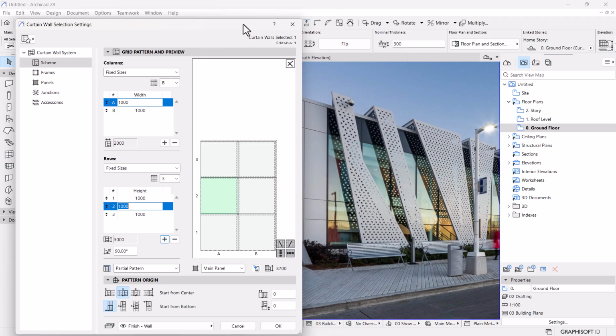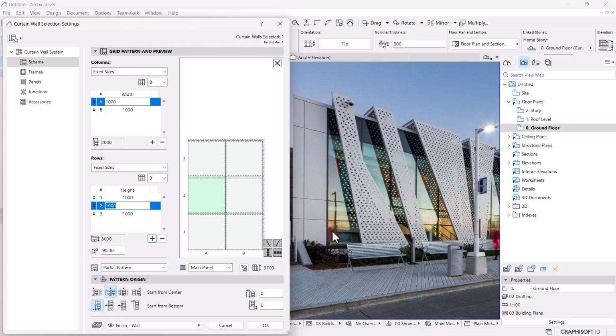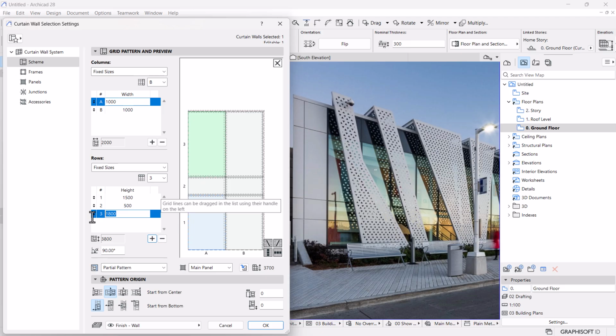And then if you look at the way this is being arranged, I would assume this one is roughly at a height of 1.5, and then this is to accommodate the height of a door, which is 2 meters, and then this we can estimate as well, maybe 1.5 to 1.8 depending on the result. So I'm gonna set the first one to be 1.5, then the following, which is 2, should be roughly around 500 to accommodate 2000 of our door height. And then the third one should be 1.8 because it's much bigger, or even 2 meters. Do you think it's 2 meters? No, I think maybe let's set it to 1.5.